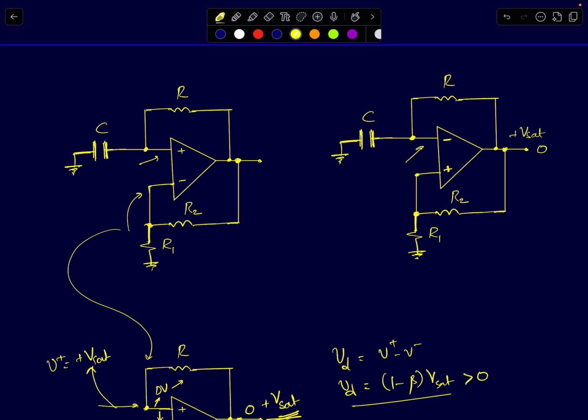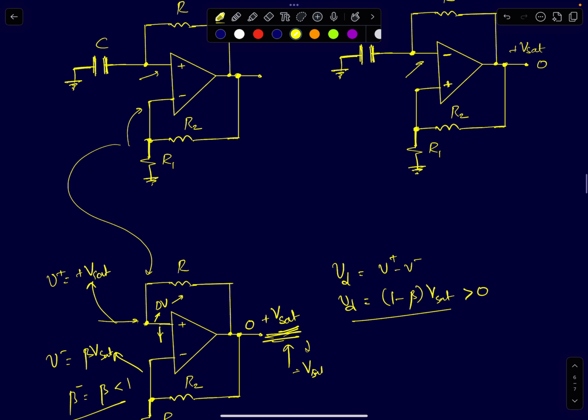It will be a purely positively fed back circuit. It will act like a latch. It will either be stuck at one of those two stable states, either at plus Vsat or at minus Vsat. There is nothing to disturb its state and change its voltage levels.